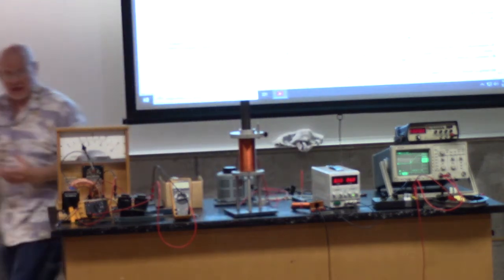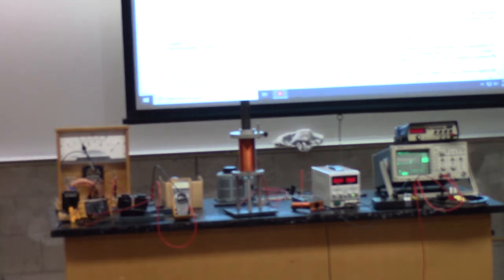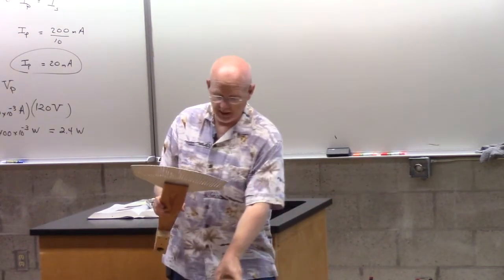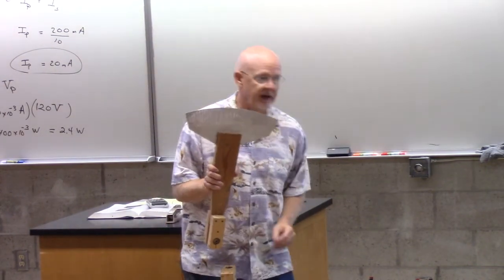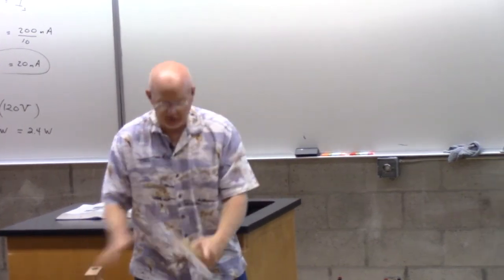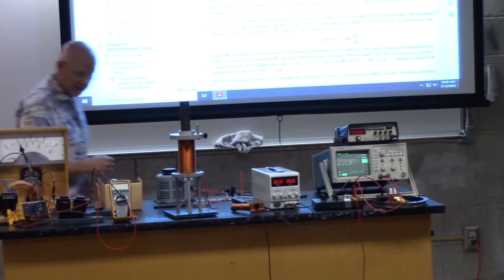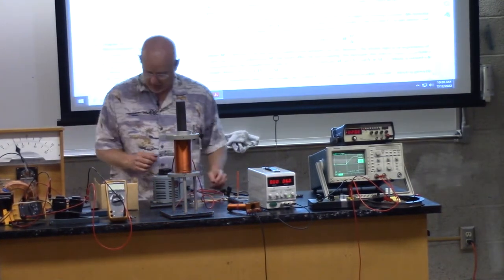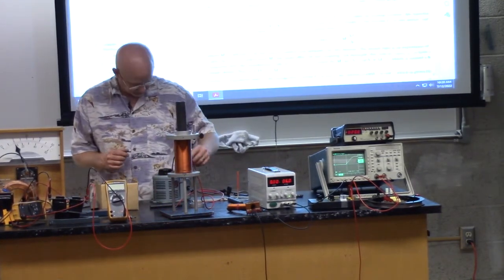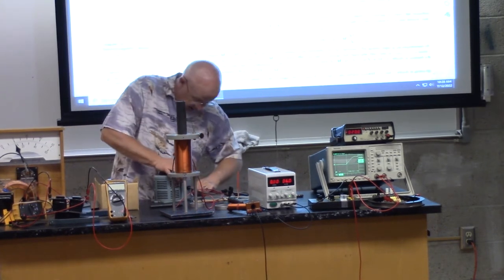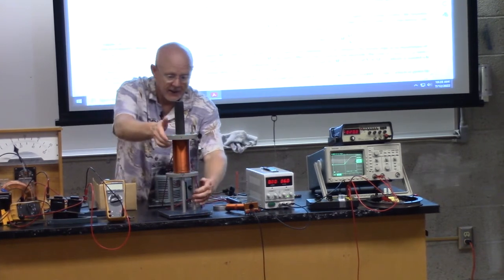It's exactly the same thing I was trying to show you between these two: this would get some eddy currents, and this one would get almost no eddy currents. There were some little ones because I didn't cut the lines that close together. But I cut them so that the current wouldn't make the little circles, and there wouldn't be that repulsion, and we wouldn't have that braking effect here. And so that is our little induction demonstration. There are some other neat things too, but I better move on.